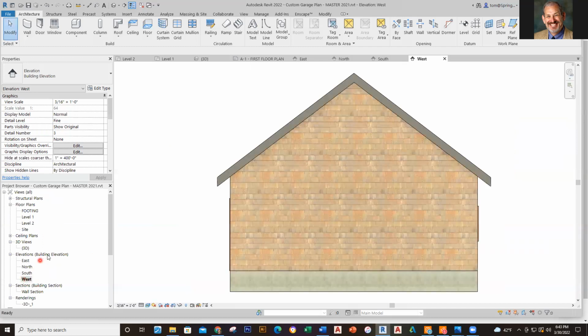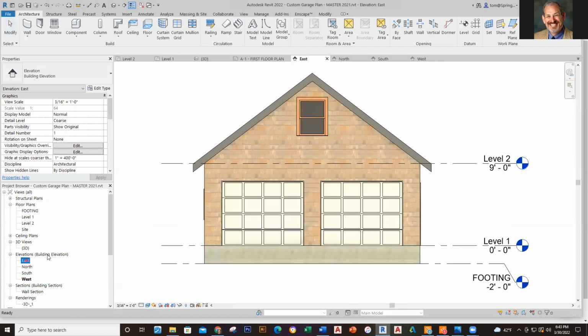Another thing that goes on when you're working with Revit is you have levels. Now levels actually are going to be the method by which Revit tracks what particular floor you're on right now. So you'll have first floor, second floor, or level 1, level 2. And those are called levels. And they actually control the vertical distances in Revit. And the templates I'm going to be giving you will be complete with those. So you won't really have to worry about that too much.